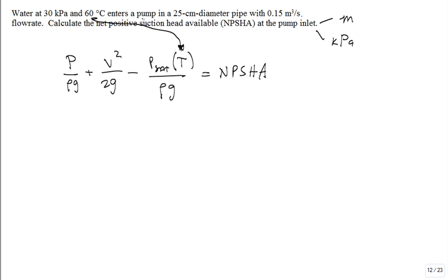Okay. So let's do the 30 kilopascal divided by 9.81 kilonewtons per meter cubed. And a pascal is Newton per meter squared. Okay, so the pascals go, the newtons go, the kilos go, and we're left with 1 meter for the units on that.